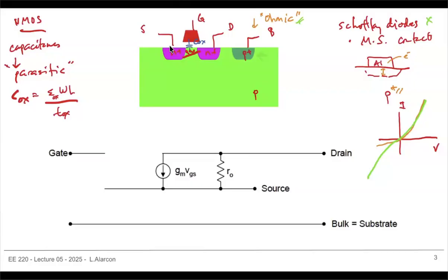And the reason why it obviously dominates is because your oxide is going to be extremely thin. Right? This is going to be in the order of double-digit angstroms or something. Basically, several atomic layers thick, and that contributes a significant amount. Right? Okay, so that normally gives you the largest capacitance over there.